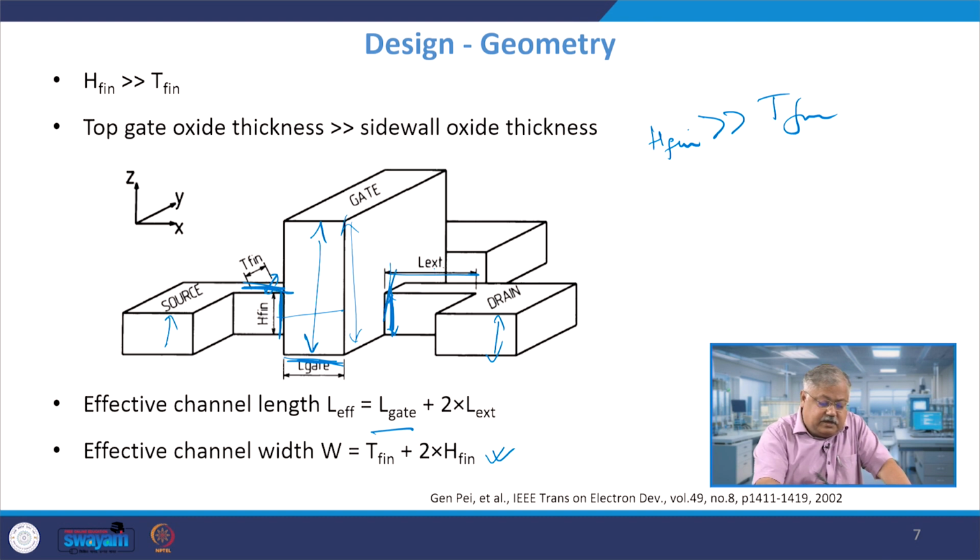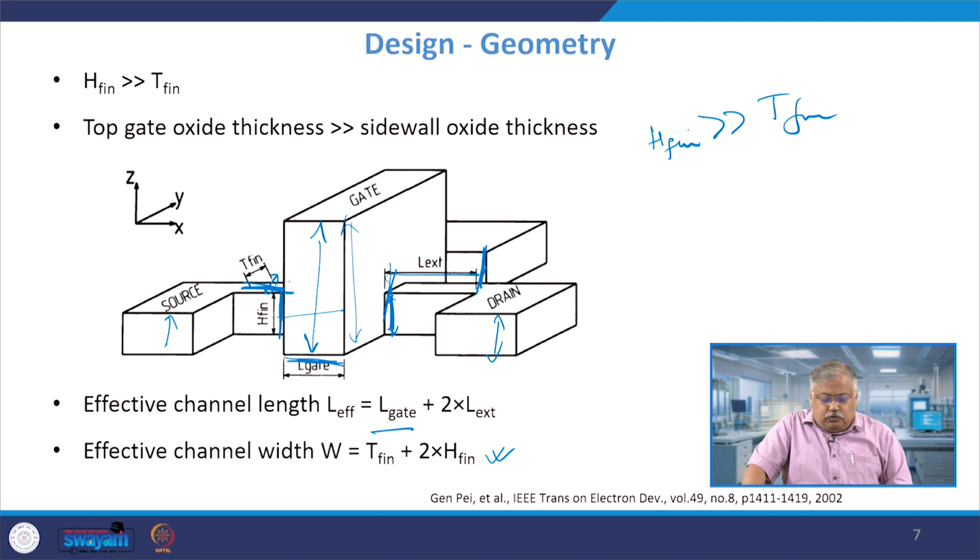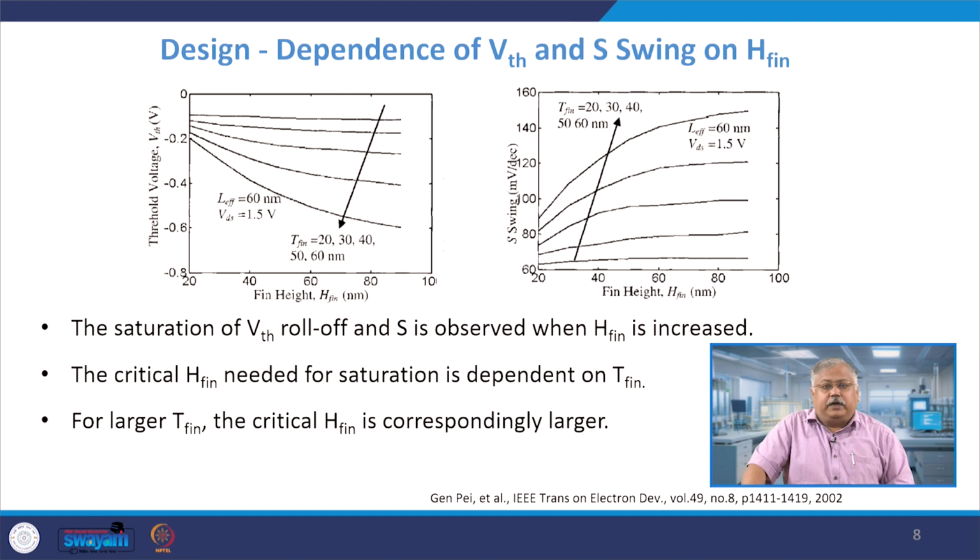The distance between the gate and the drain and between the gate and the source is basically referred to as extension. And you can insert quite different types of materials here, known as spacer materials, in order to improve the design characteristics or electrical output characteristics of the device, and this gives you quite decent input output characteristics of the device.